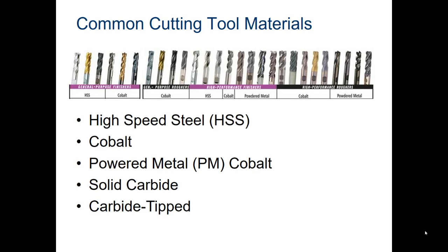It cuts really well. However, the problem that carbide tools tend to have is A, they're expensive, and B, they tend to be a little bit more brittle. So they tend to shatter a little bit. Not necessarily like the whole tool breaking, but just the edges or the cutting edge will break off. Instead of wearing down and needing to be sharpened, they'll just chip away. And so that's the problem that you see with those. But they're definitely good for cutting heavier, again, harder materials, denser materials.